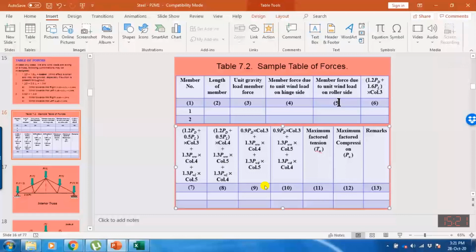You need to understand that columns 4 and 5 are just numbers, because I could not write the complete sentence, so rather I am writing column number 4 and 5. That number could be different. And I told you that you have to add these 4 columns again, because these 4 columns are for PWW1. Then you have to add these 4 columns again for PWW2, because we have 2 windward loads depending upon our orientation or the inclination of the rafter.